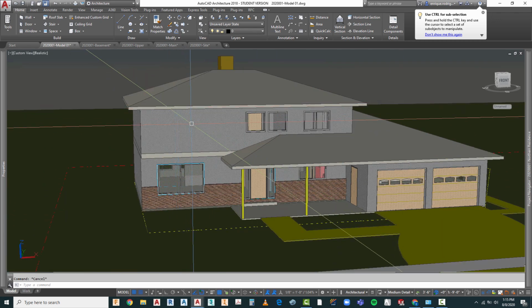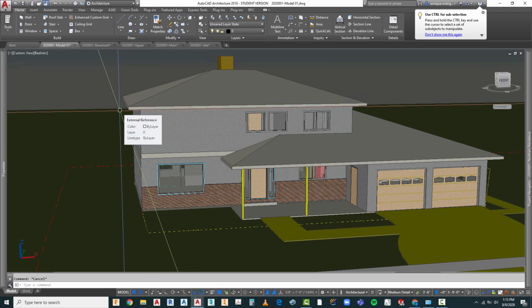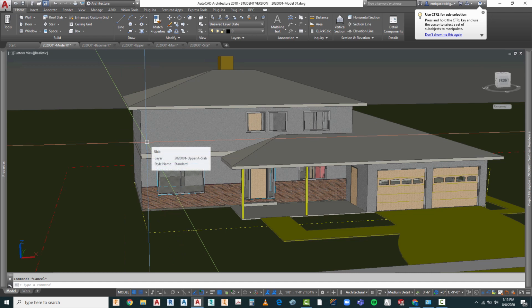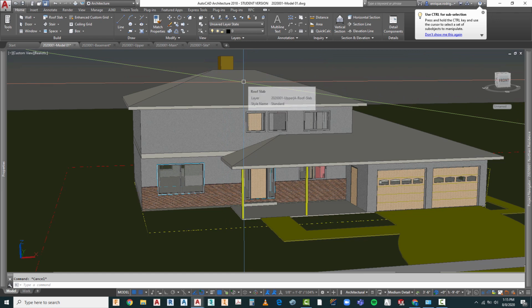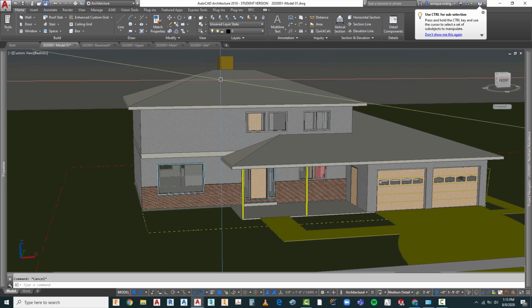But as an example right here, if we take a look at this roof, we could add a fascia board and maybe some gutters located in there. And also, we could draw some downspouts. One of the reasons we may want to do this is because through some simple extrusions, we would be able to modify all three or all four elevations that we need to develop. The same thing with some trim work at the top of the chimney, including maybe a chimney cap that we can download from a website of a manufacturer that may be producing those.